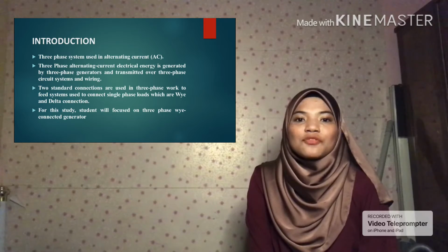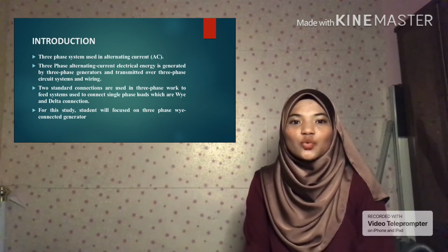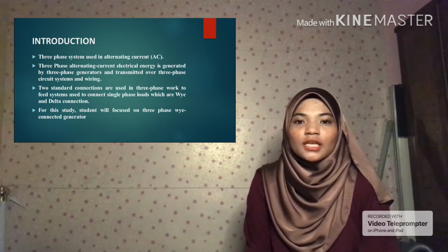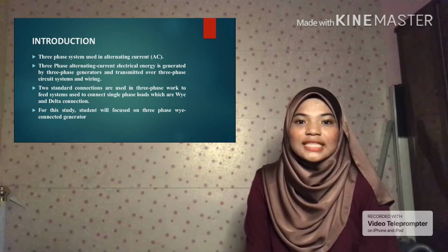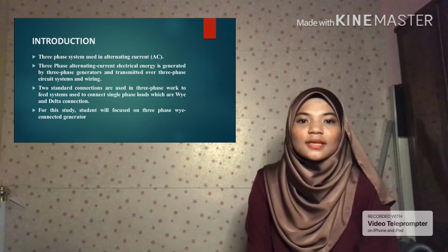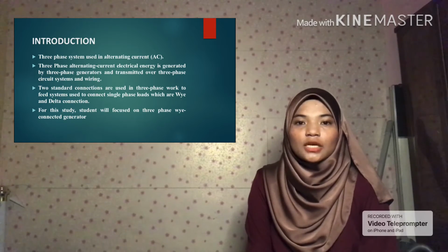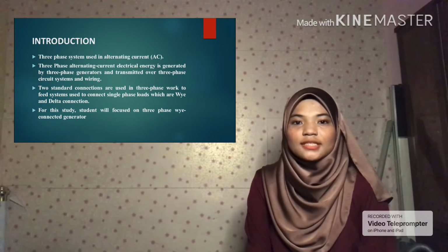We can see a three-phase circuit as three single-phase circuits consolidated into one circuit system with either 3 or 4 wires. Each one of the phases or waves generated can be separated using 2 wires only. Using this single wave, single-phase motors and other single-phase loads may be operated from a three-phase circuit. In industrial operation, or whenever it is available, three-phase circuits are preferable to single-phase circuits.